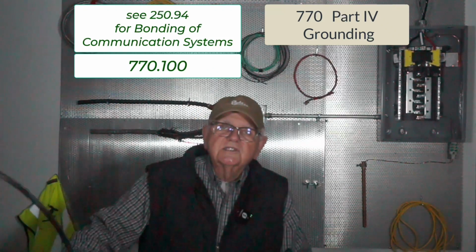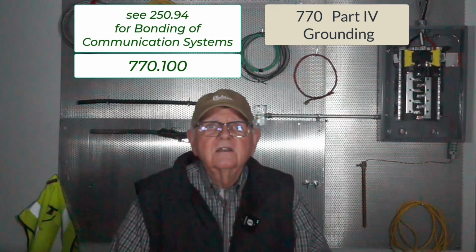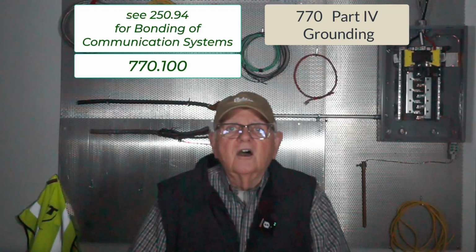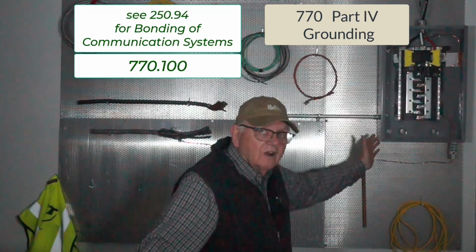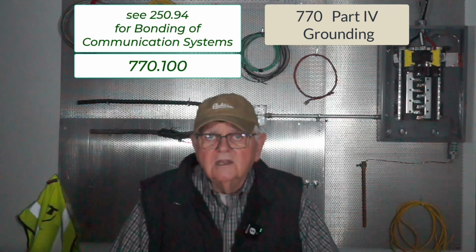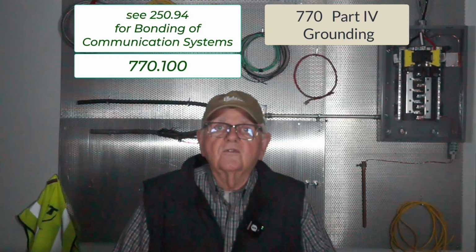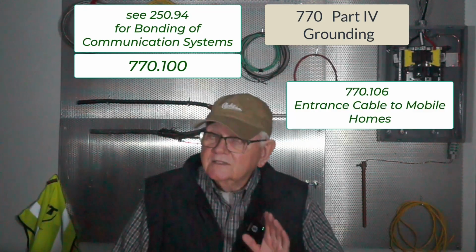So in 770.100, we're going to find that there are 7 different locations of where we can connect it. Perhaps it's the enclosure for our service and so forth. So anyway, if you get into that situation, which you may well if you're installing this cable, then take a close look at 770.100. Lots of rules in there, righty? If I'm going to a mobile home, that's a little bit special.